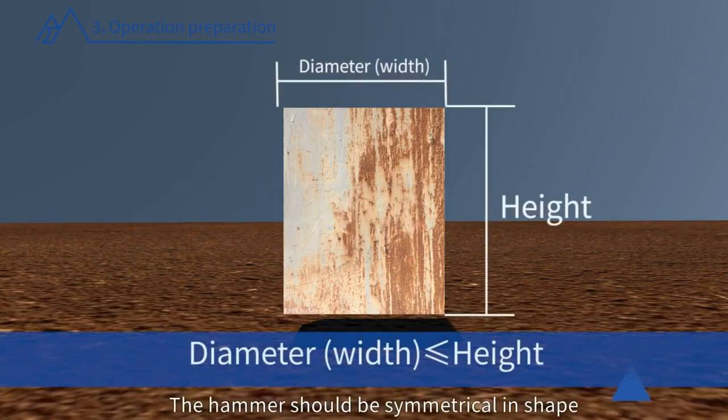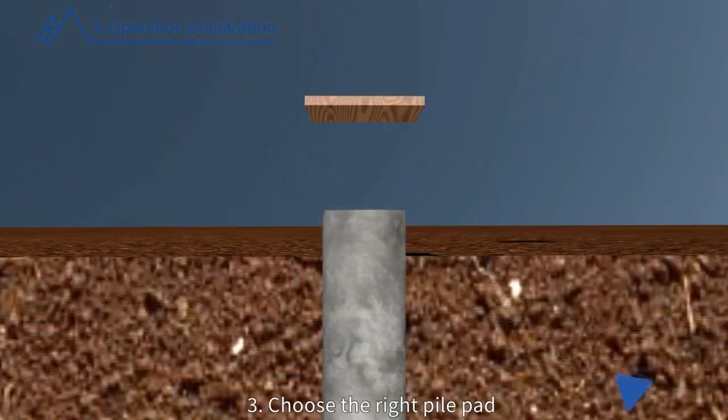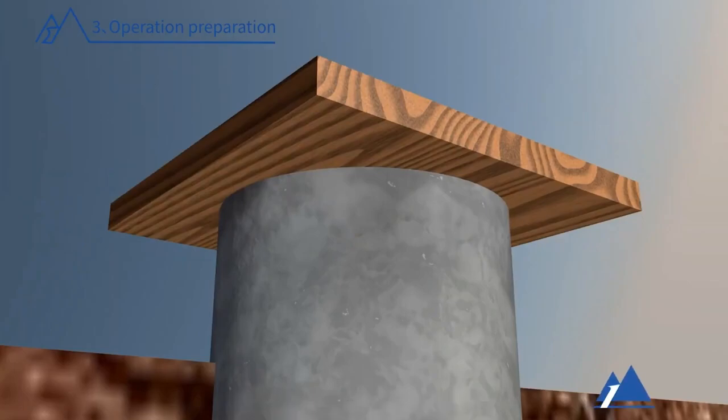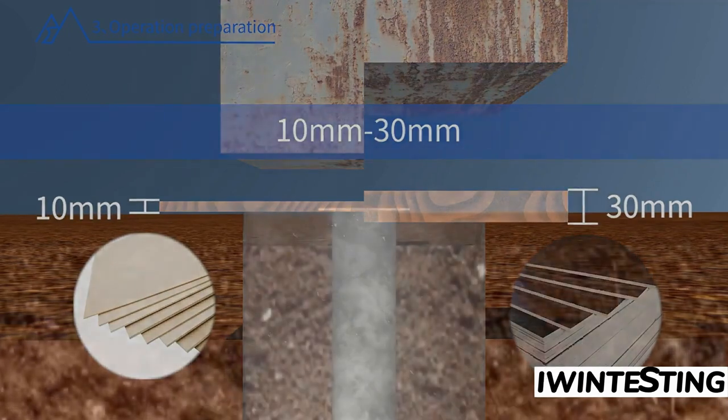The hammer should be symmetrical in shape, and the ratio of height to diameter or width should not be less than 1. 3. Choose the right pile pad. The pad size should be slightly larger than the pile top section size. The pad can be made of wood or plywood with a thickness of 10 mm to 30 mm.